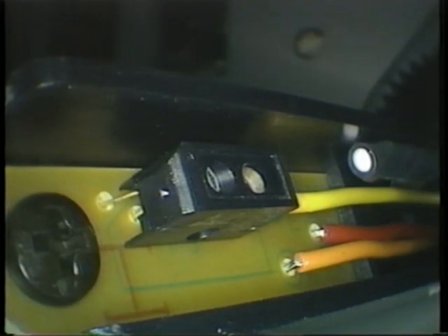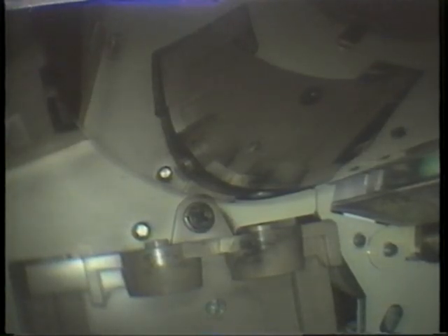This type of system exposes and develops a small test patch on the photoconductor once about every 10 copies. A photosensor checks the density of toner on the test patch by reading how much light it reflects. The brightest reflection would be from the bare drum surface and the darkest from a very thick coating of toner. If the patch isn't dark enough, that means there's not enough toner in the development unit to provide a suitable concentration in the magnetic brush.